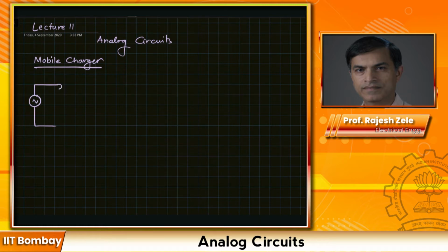And then we have a transformer that looks like this. And the transformer has a primary and a secondary, which is a step down, of course, because at the input you have 230 volts RMS going in, 50 Hertz in India. And then the first circuit that's right after the transformer is what uses diodes, and we're going to talk about that today. The waveform which is showing up at the secondary is generally an AC waveform, and we would like to convert it to DC.